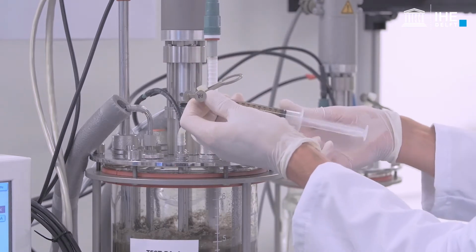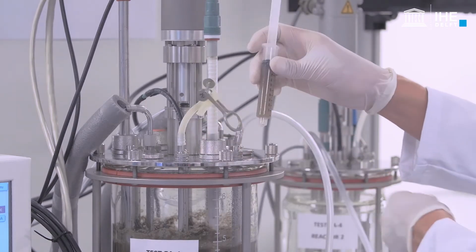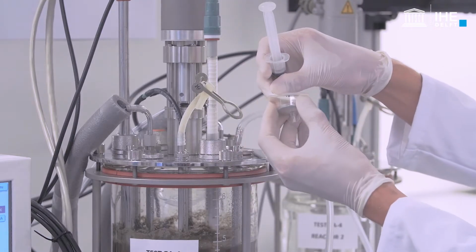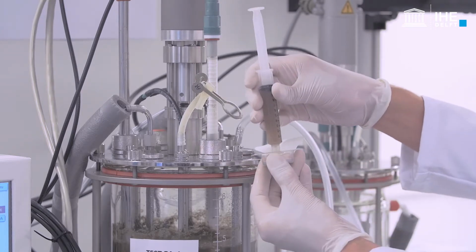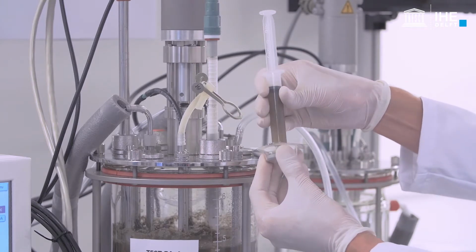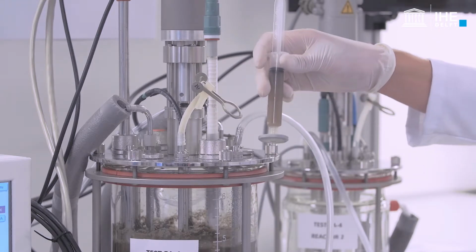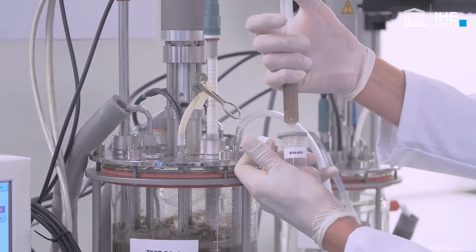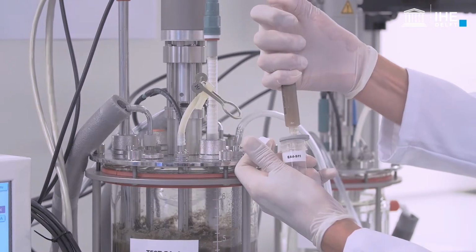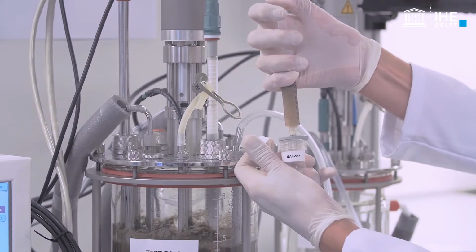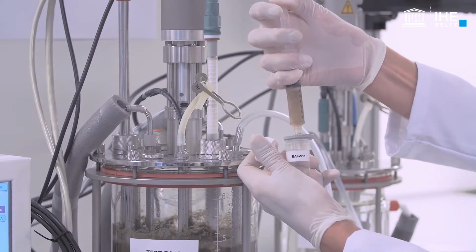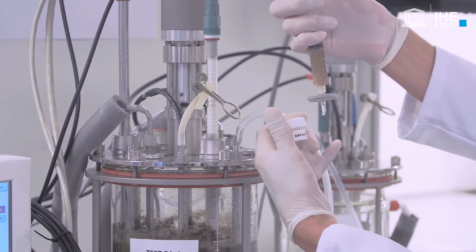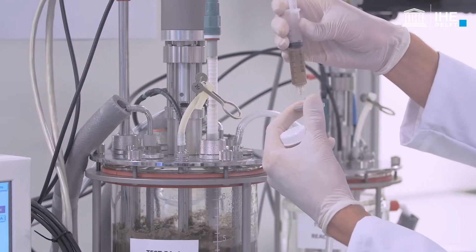Collect the last filtered sample of the anaerobic stage to determine the final concentrations of the soluble compounds of interest, like soluble COD, acetate, orthophosphate, and ammonium, as planned in the working sheet. Remember to prepare enough filters and filter the sample carefully. The concentrations measured at the end of the anaerobic phase will correspond to the initial concentrations of the subsequent anoxic and aerobic stages.